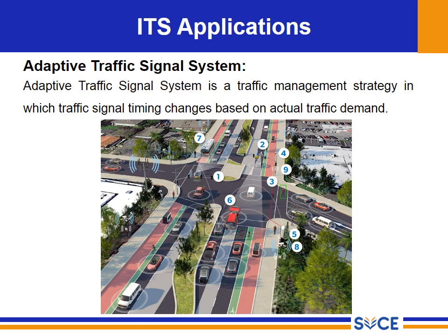Next important thing is the adaptive traffic signal system. Suppose there are signals nearby on urban roads. Since the strengthening operation is done on only one side of the road, one side of the junction, the queue length may be much more. So based on the queue length, it gives more green time where the work is actually taking place.